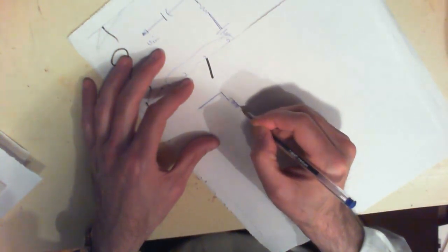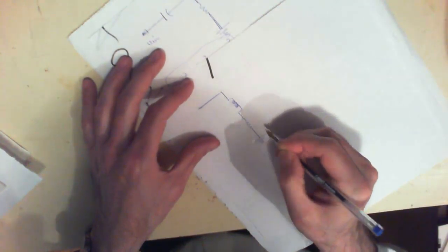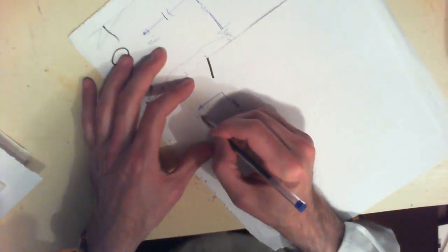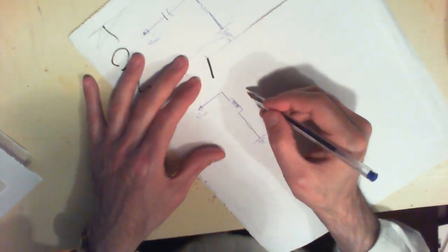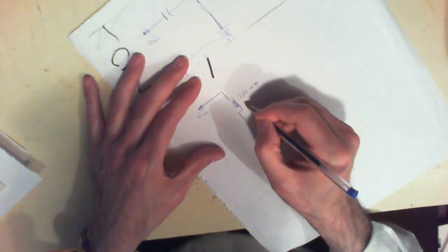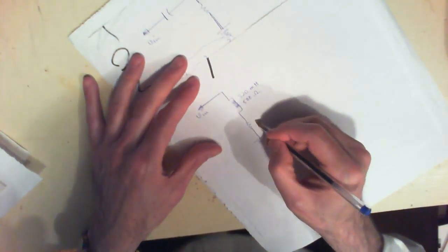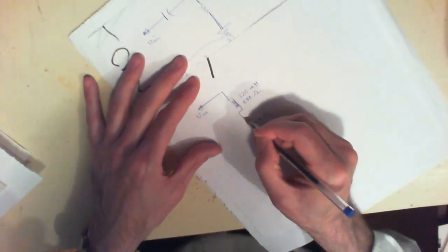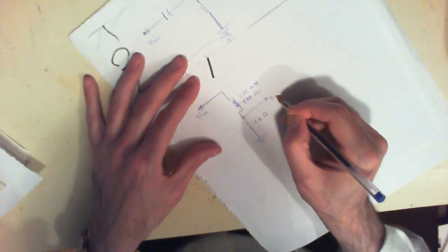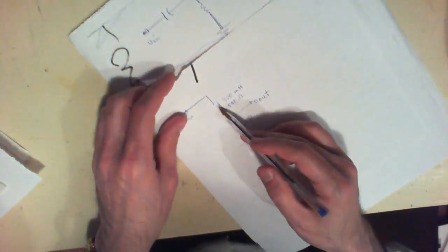So this is an inductor going to a resistor, and that's connected to the ground, and this is your V of in, and this is 320 millihenry, and the resistance is 500 ohm. This is 1 kilo ohm. This is your V of out. Okay, and this is again the same story. This is a low pass filter, right?